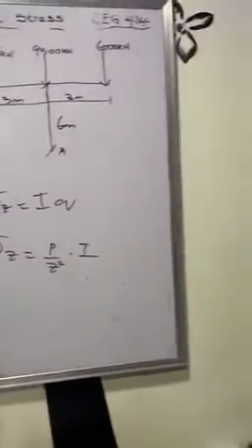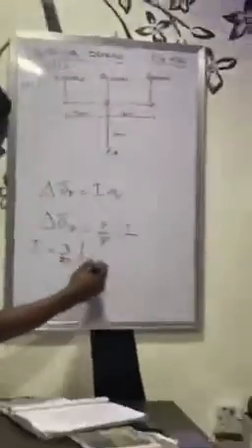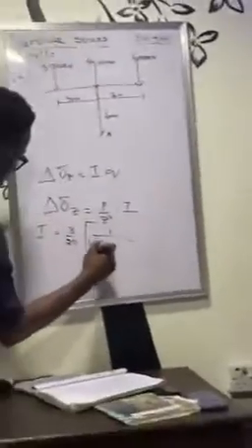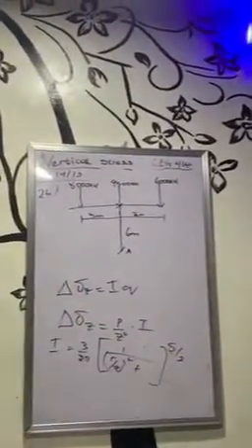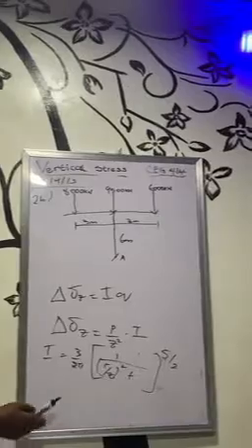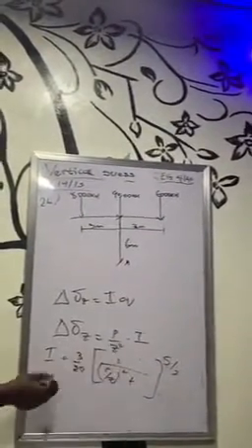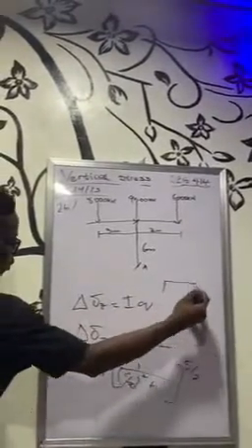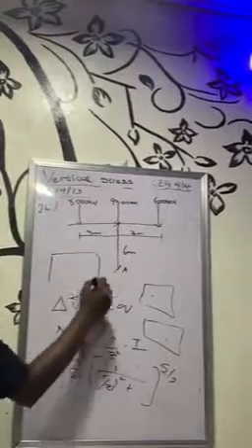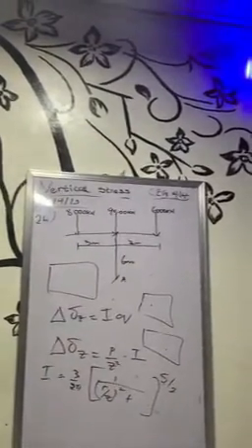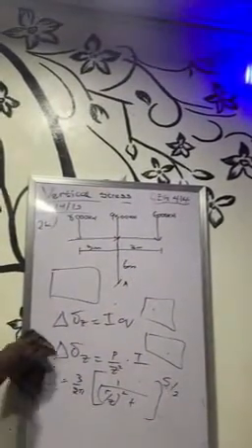Multiplying I, where we had I as one long formula that had 1 over r over z squared plus 1, to the power 5 over 2. You can learn this, so I advise you learn this. You can also use tables to just find this. So we did for point load, we did for rectangular loaded area, we did for rectangular loaded area at the center, we did for rectangular loaded area at a point that's not the center, we did for rectangular loaded area outside the rectangle.